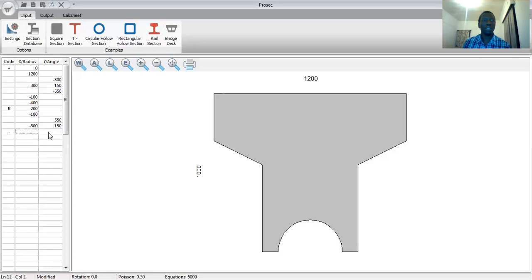So basically, minus, and the starting point of that circle is the center of the circle, which we got as 300 in the x, minus 150 in the y. So that's our starting point for that circle. Then we go to the next line and change the code again. These codes, you don't have to cram them. It becomes second nature, like it is for me now. I just know it's a void, that's the starting point because it's a circle, that's the center of the circle. Next line, I change to C for circle. And now I'm dealing with radius, not x dimension. I'm now dealing with radius of 50. There you go. Pretty easy.